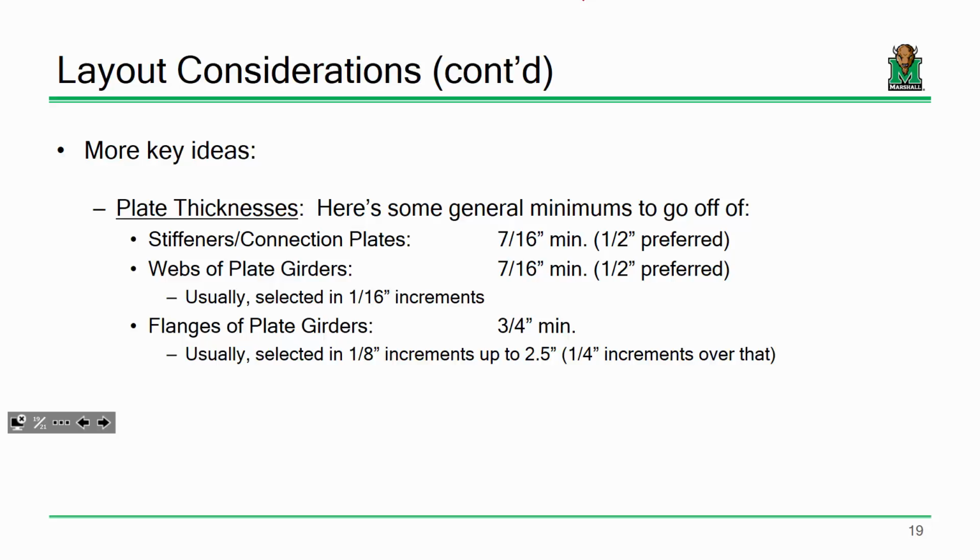If you're the design engineer, are you going to spec out a 19/64 plate that's going to have a lead time of 6 months? Why don't you just spec out the 1/2 inch plate or what have you, and you'll get it in 4? Make sense? So make sure you're using a little bit of common sense on your dimensions.